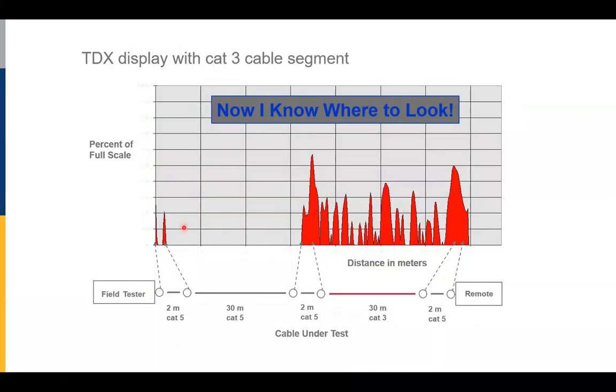Now, within the cable tester, we have a functionality called, you may have heard of TDR, time domain reflectometry, that we use to find the distance to impedance variations. You may have done that on telephone cables if we wanted to find the distance to where a telephone connection perhaps had some corrosion with it. Well, we have TDX, which is time domain crosstalk analysis.